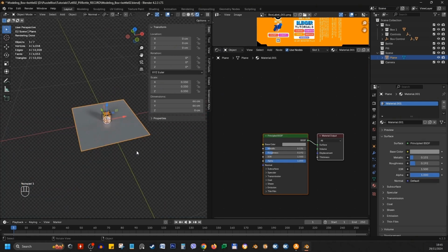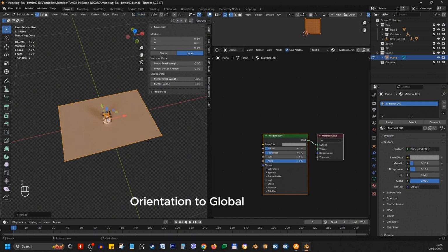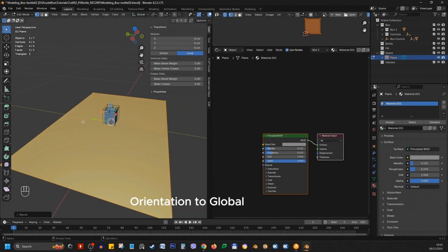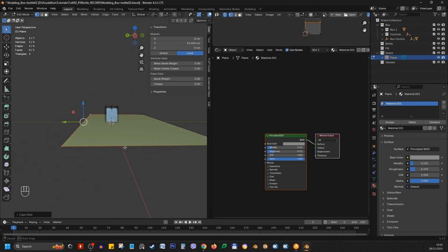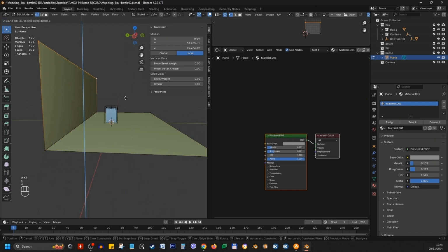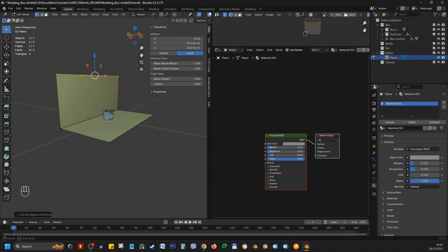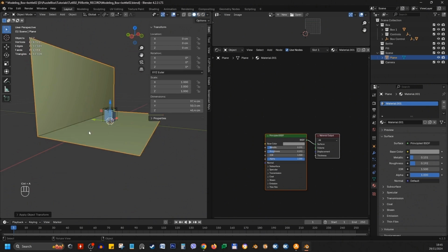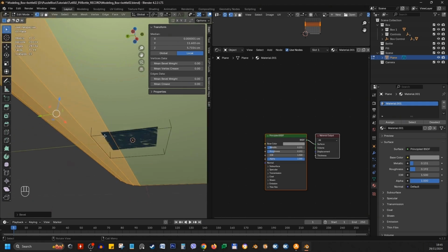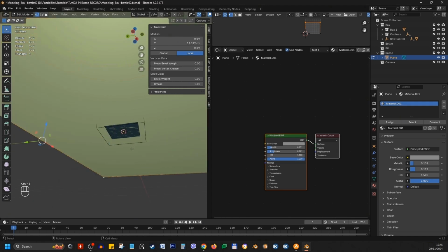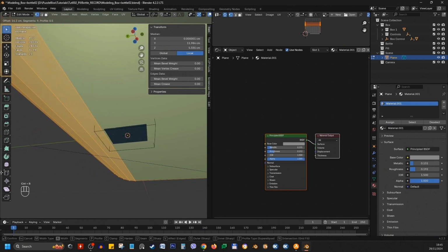Go into edit mode with the plane selected. Bring this back edge closer to the box. Hit E Z to extrude it upwards and bring it up. Select this edge here and hit Ctrl B. We want to bevel this edge. By scrolling on the mouse, I add more or fewer cuts. Let's add in 9 segments and have this final line of the curve very close to the box.